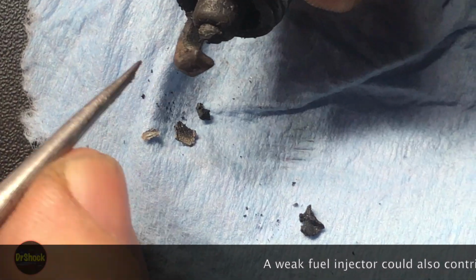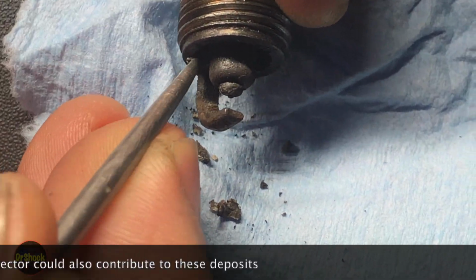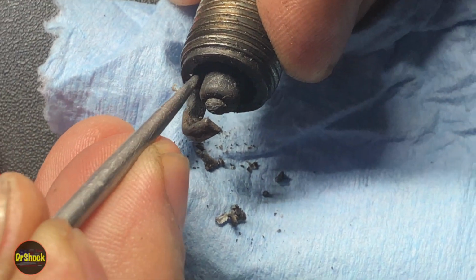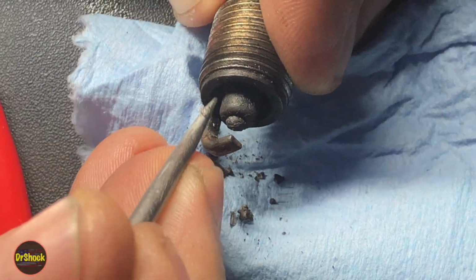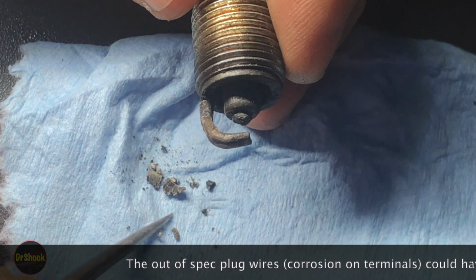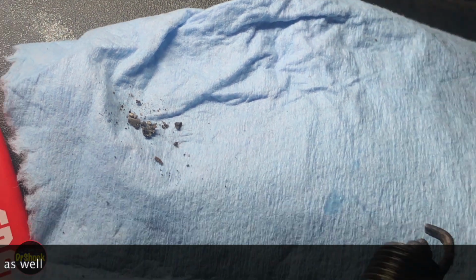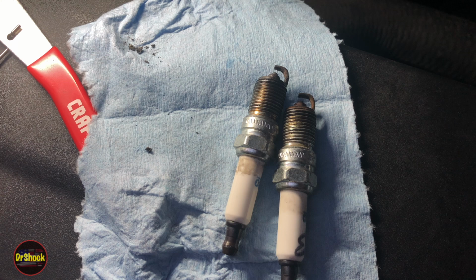And what I think happened to this plug, this carbon either shorted this electrode out or started to get it arcing way up into here past the ceramic. And that's why I think we eventually got the plug just not reliably firing, and that led to the misfire condition. But all of that is carbon from oil burning. So that was all it is. Sometimes it's something simple. You don't need a new coil. You don't need to hit the fuel injectors. You don't need to do anything like that.